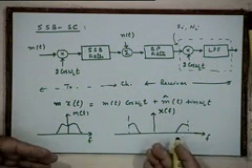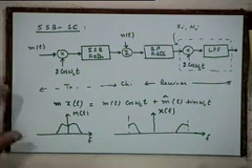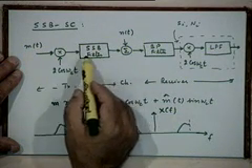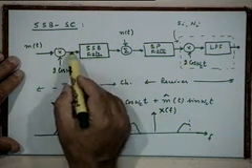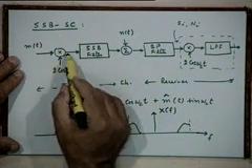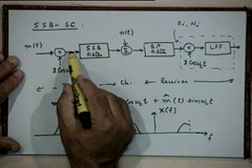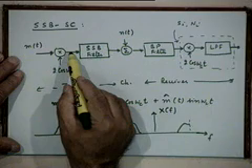That's if you are considering lower sidebands. If you are considering the upper sidebands, it will be the other way around, right. So corresponding to this message spectrum, you have this. So what is the power of the message signal? That is, what is the power of 2 mt cosine omega ct that you have here? What will be the power here? It will be 2 m square bar, isn't it?